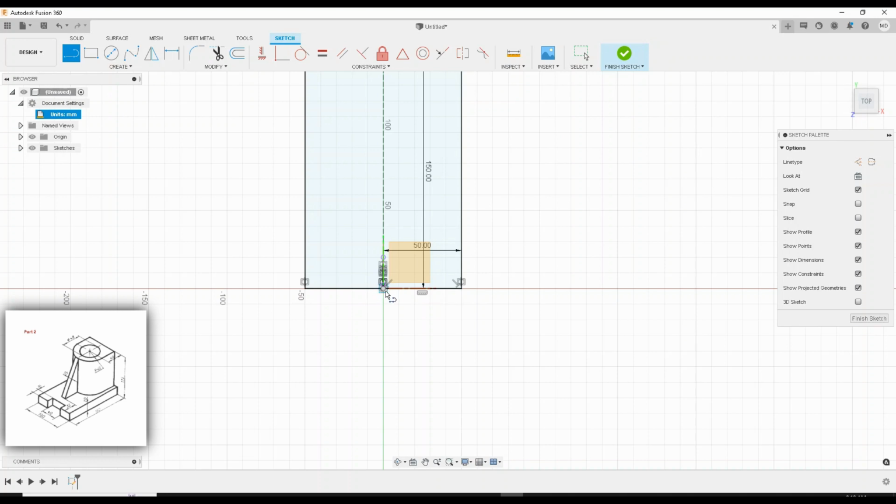We're going to do the origin since we started at the origin of the grid. Go over 20, press enter. 20, press enter. Okay. And then the width of that little section there is going to be 16. And then you just do the same thing here.